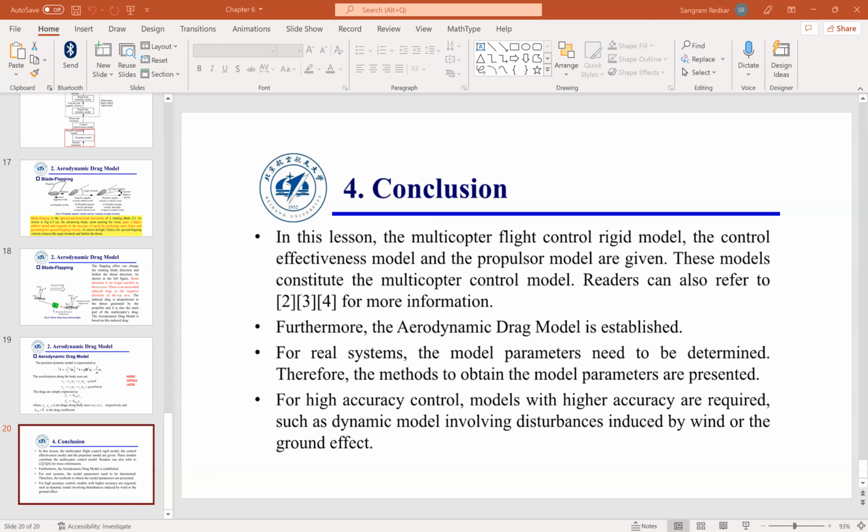Let that sink in. This is an entire field, and I spent my 2 years working in that area of inertial navigation and tracking, dealing with just these equations. Put an IMU on aircraft and find out the orientation of the aircraft. You realize that you cannot solve this equation by just plugging the numbers on the right. It's a differential equation, which means you need to integrate. You agree with me? Here is the problem with integration. Every time P, Q, and R will be changing because your aircraft is rotating. So what you need to do is numerically integrate, and then there is a problem. How would you find out sine phi, cosine phi, sine theta? You will find those from the previous angles of attitude. I would let this sink in, and we'll stop here.